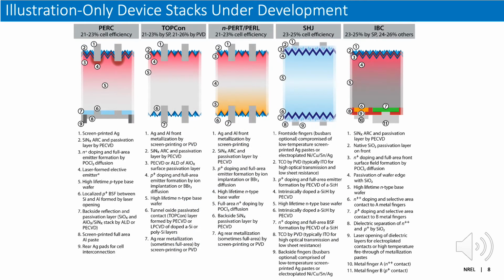So now that we have wafer production modeled, we can then proceed to cell fabrication or cell conversion. Here I'm showing our reference designs for 5 cell types. I'm not going to discuss all 5 in the interest of time, but I just want to note that these architectures vary in terms of their wafer polarity, efficiency, current market share or scale of production, and other features such as bifaciality, which all affect their TEA performance. The PERC cell, or passivated emitter and rear cell, is currently the most widely produced cell type, so I'm going to briefly review the PERC conversion process in the next slide.